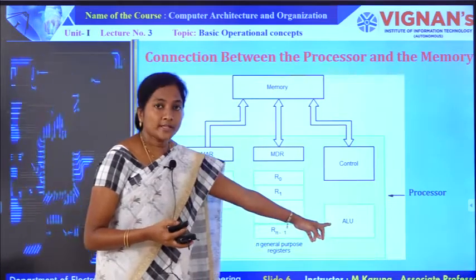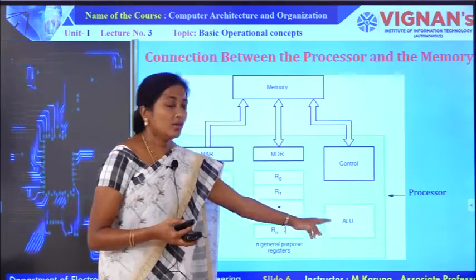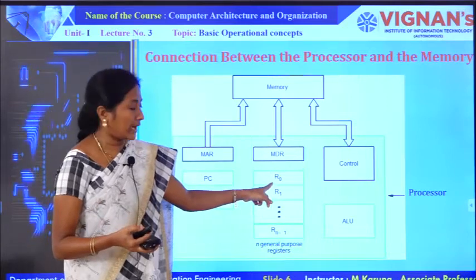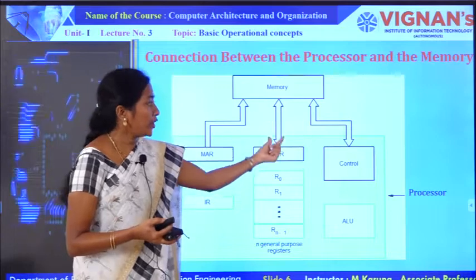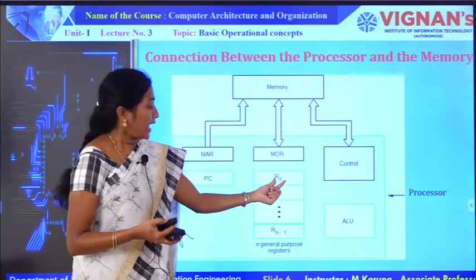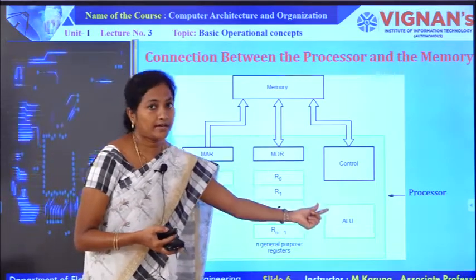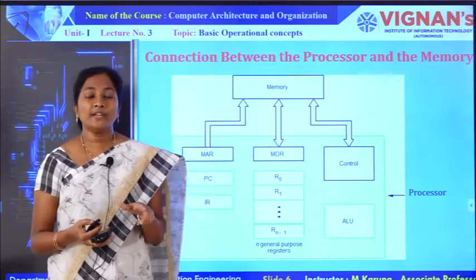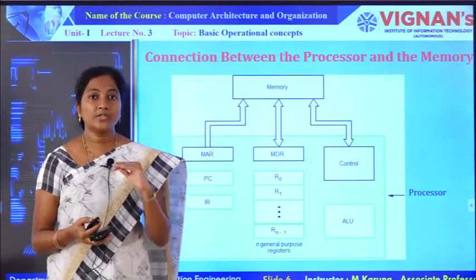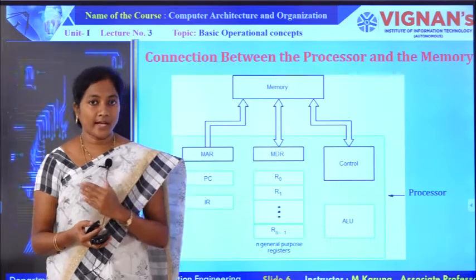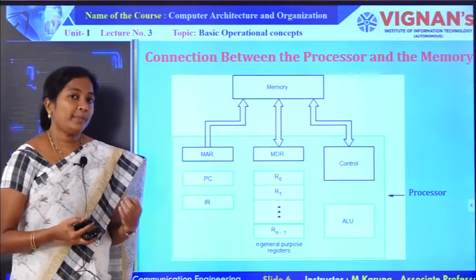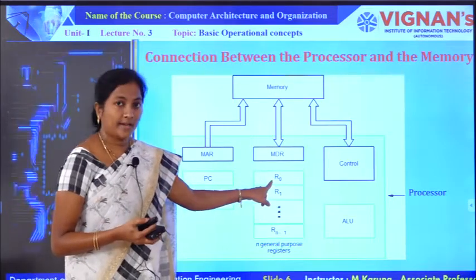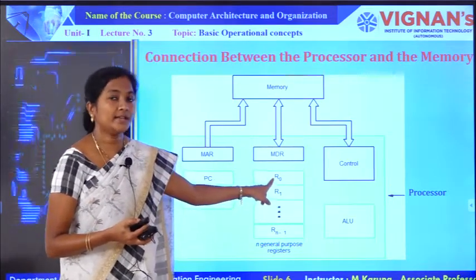Now after that, the processor, or we can say ALU, collects the other data from R0. Now ALU got the data from the memory location labeled by LOCA and from register R0. ALU performs the add operation between the data stored in LOCA and R0. After performing the operation on that data, the output will be transferred to register R0. That is the instruction format.